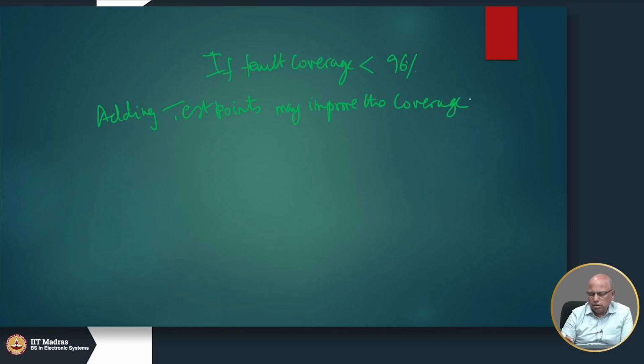So, it depends on how many test points you add. If you add too many test points, people will not be very happy because you are asking for too many pins and performance may get degraded. So, that is a little bit of an optimization problem. You have to add the right test points, so in all this testing you will find a lot of optimization problems. These are hard optimization problems.